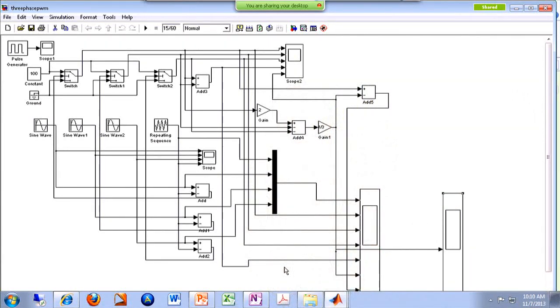So what's happening is, this is my leg A basically. This switch is that single pole double throw switch which behaves like those pair of switches S1 and S4. And this is leg B and this is leg C. And how do I make the decision of should I be in the top throw or the bottom throw?